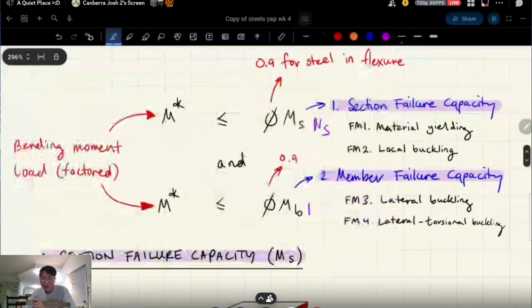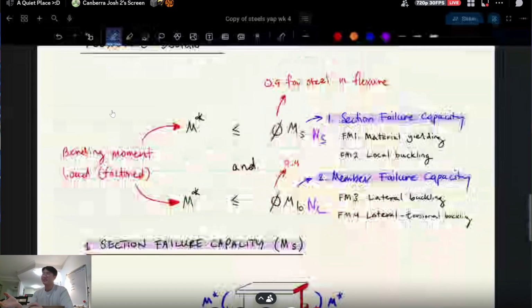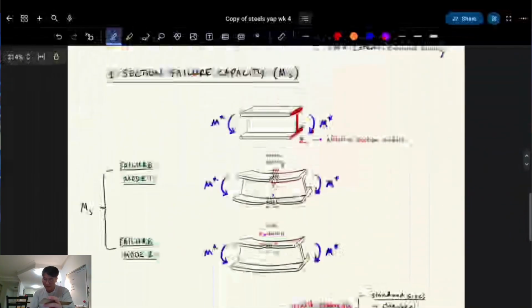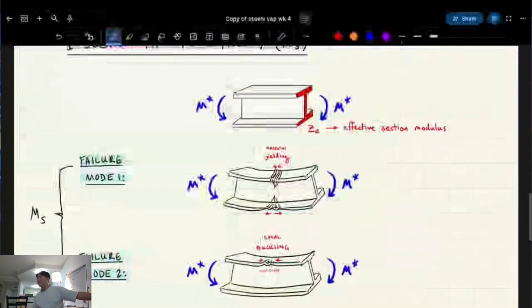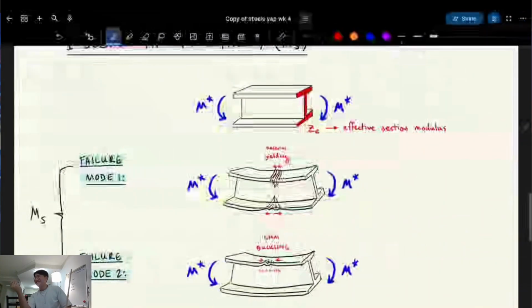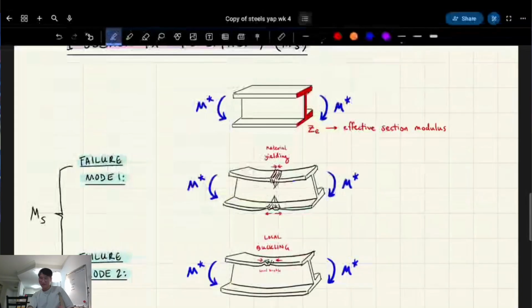But they're both buckling. One's Euler buckling and the other's lateral-torsional buckling. Here are some drawings, but hopefully it just re-emphasizes the point. But this is for section buckling, which we haven't really talked about too much. We've mainly talked about lateral torsional buckling. It can buckle in section, but we have to calculate the section capacity first, just like for compression, and then we have to go to the lateral torsional buckling. Okay.